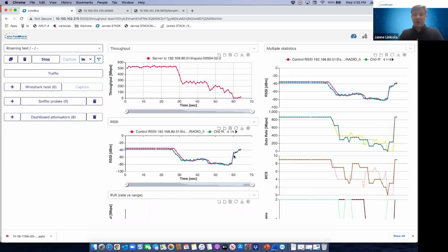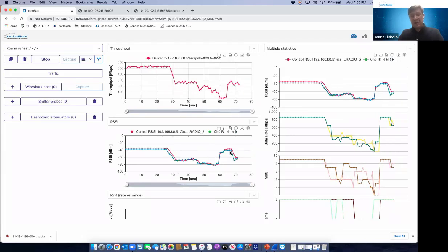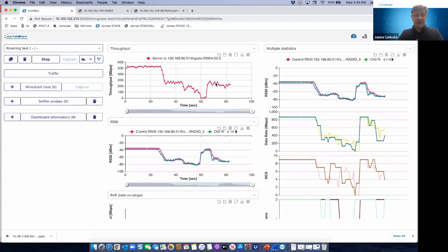And here we see the first steering event. We suddenly got a very good RSSI here, which can really only mean that we were steered to the extender by the mesh network. And as you can see, we get the 250 megabit per second speed that we saw on the previous demo, so everything's consistent so far.